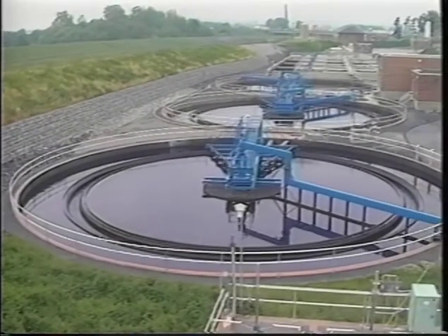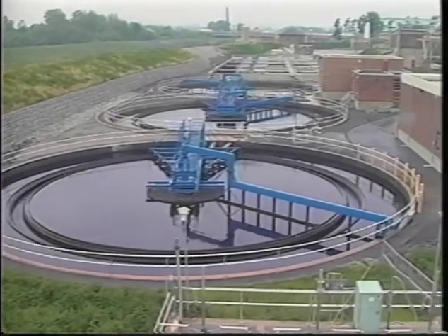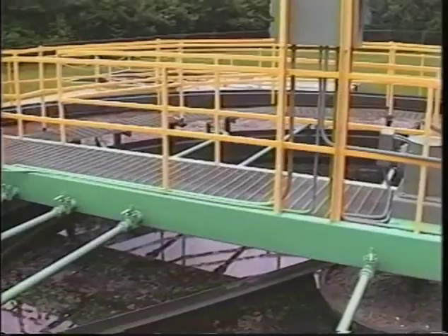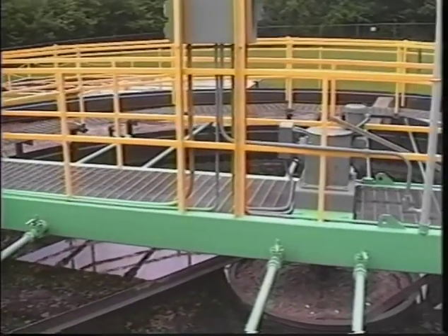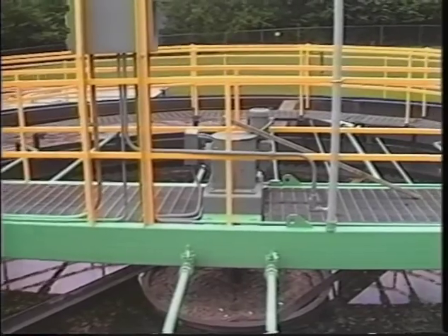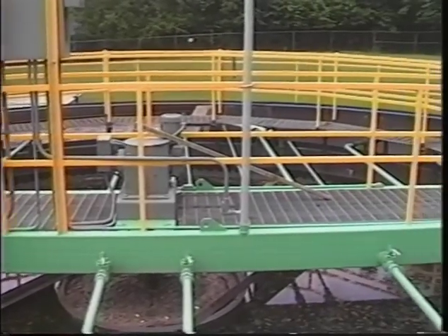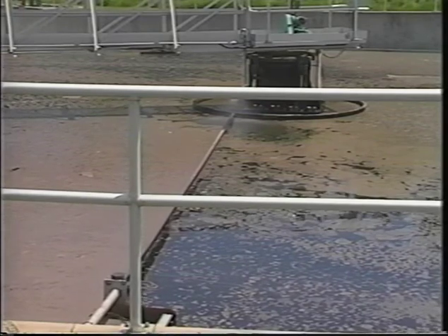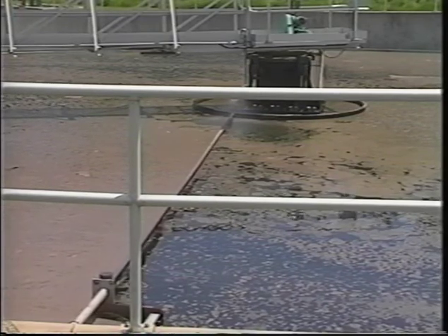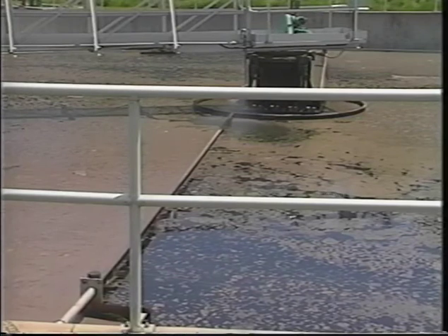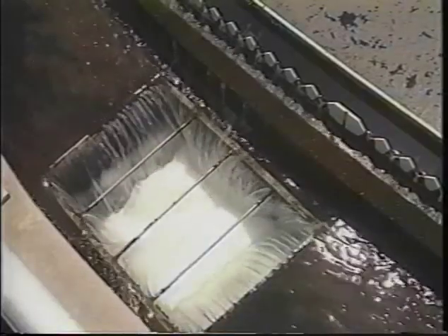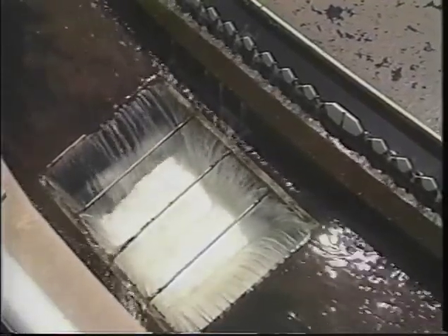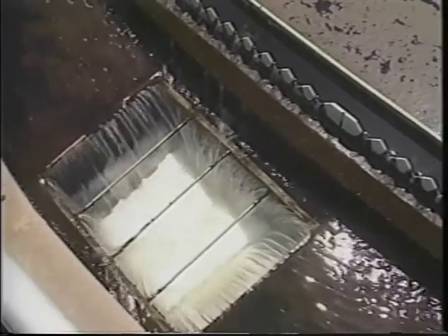Now, let's take a look at the final major component, the clarifier. This unit will usually be constructed of concrete or steel and may be round, square, or rectangular depending on the design of the system. In the clarifier, the hungry activated sludge microorganisms are allowed to settle to the bottom while the clear treated wastewater is decanted over effluent weirs.